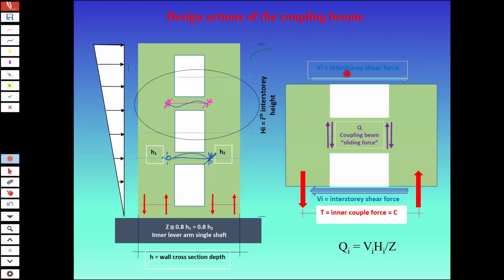Well, you can imagine how demanding this building is, because you know this is actually a cantilever. Okay, and here on the top the shear force is 0. As you go down, you add portions of that. So the more you go down with your coupling beams, the higher this will be.